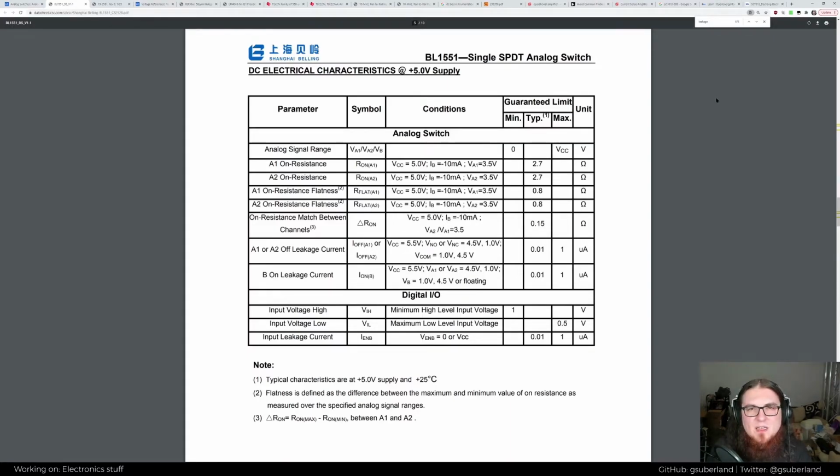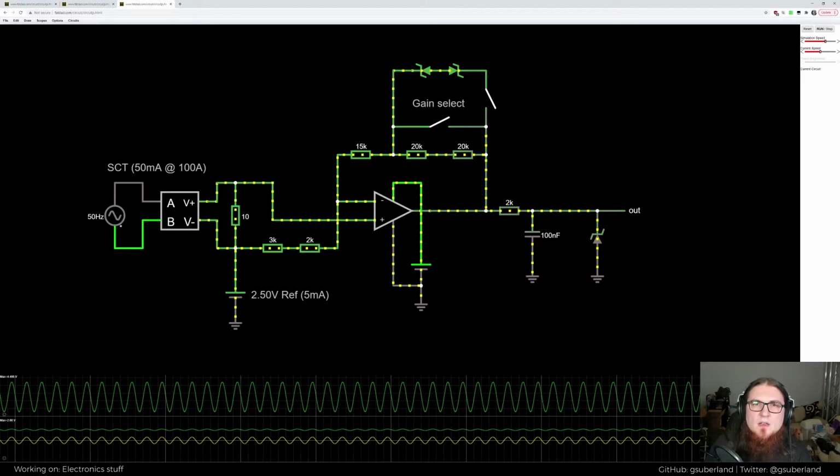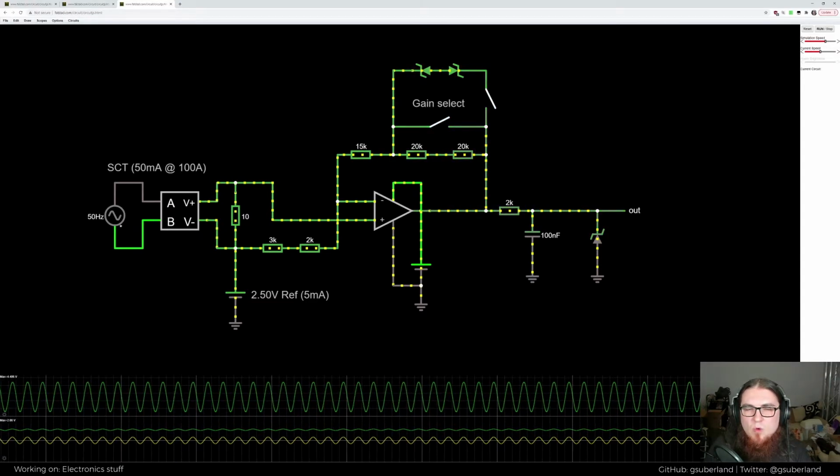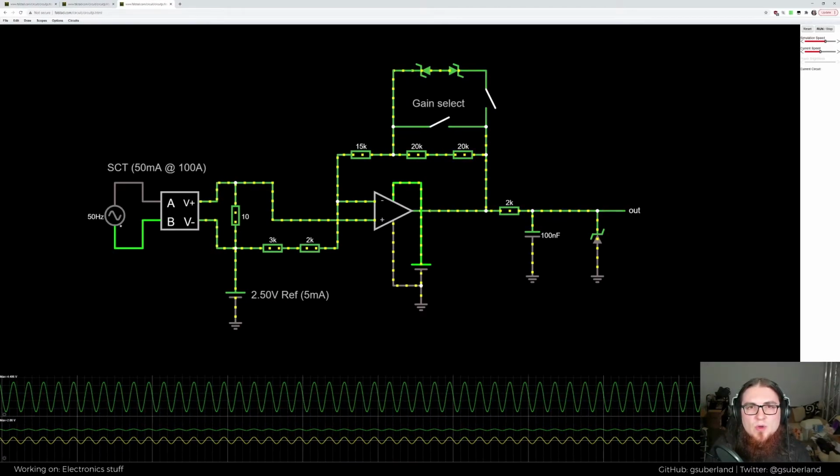And if we go back and look at the circuit, we can start to see why. So if we look here, imagine that when this switch is switched off, there's 1 microamp still flowing through here. Now, if we use Ohm's law, we can think about that in terms of resistance, because we've got a voltage and a current. So when you plug the numbers in, if we've got 2.5 volts flowing through here, you effectively get the equivalent of a 2.5 mega ohm resistor across these two resistors.